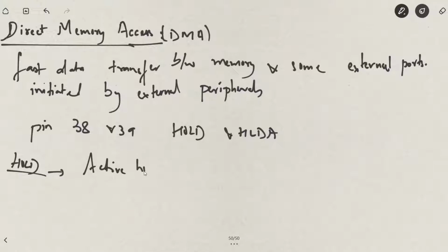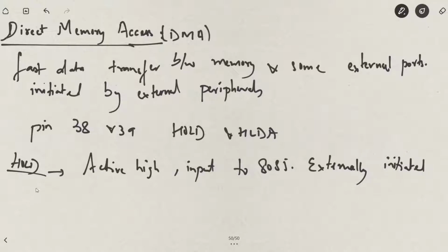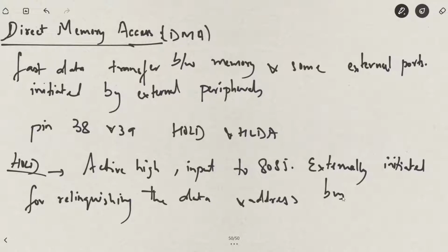Active high input to the 8085. It's an input pin, so it is externally initiated, for relinquishing the data and address bus of the 8085 to the external peripheral.